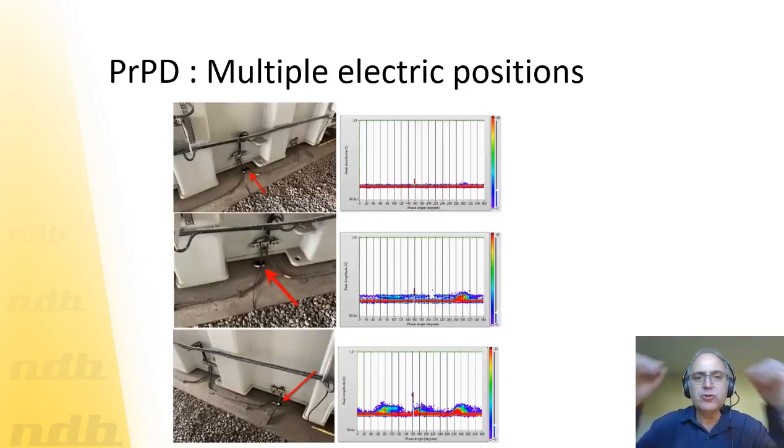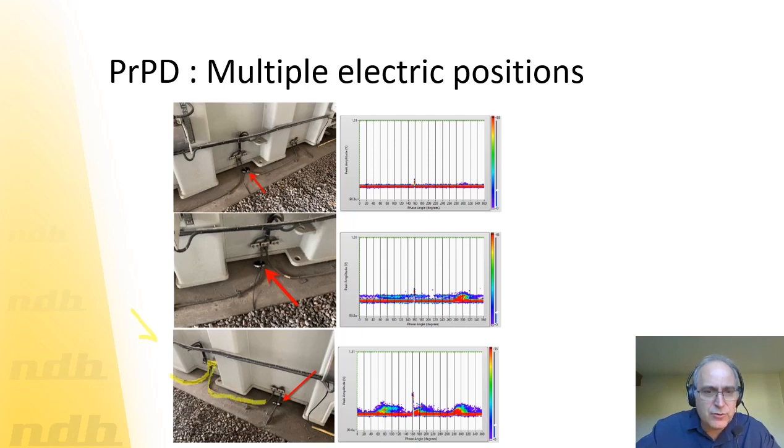Just one point, because before going to the second one, this is a real example. This is a real case. I made it myself. You can see on the picture that the ground strap is distributed over the transformer. See the picture on the bottom here. We have a ground that goes to a connection bar and another ground that goes to a second connection bar, and that connection goes to ground.